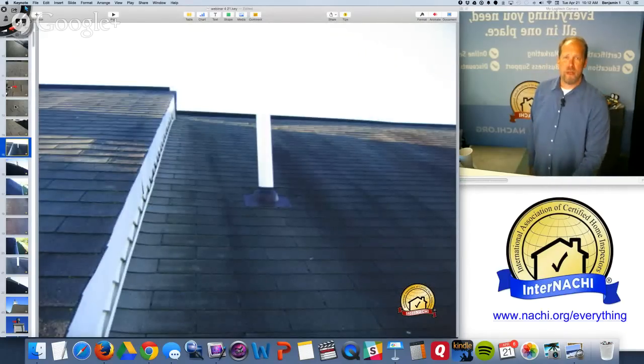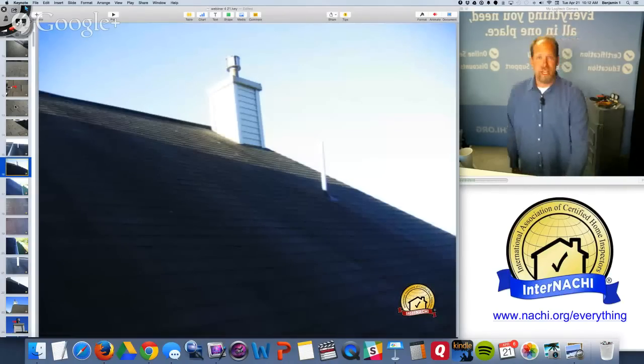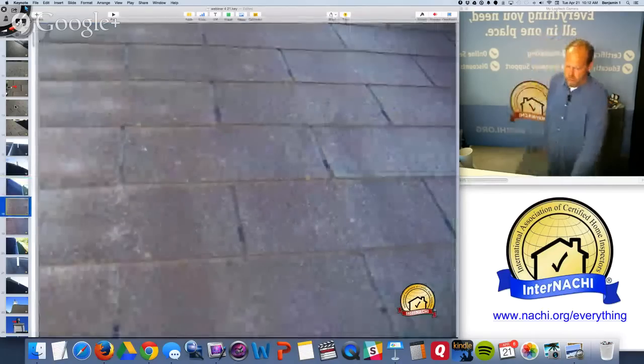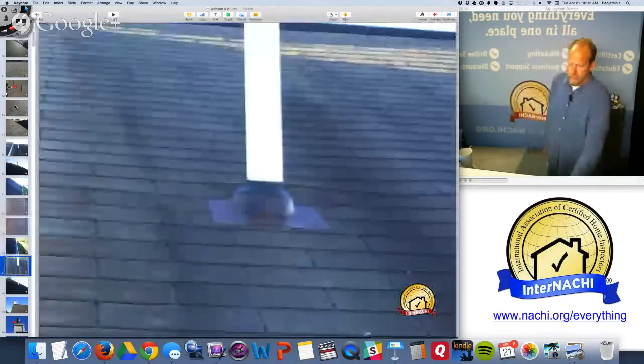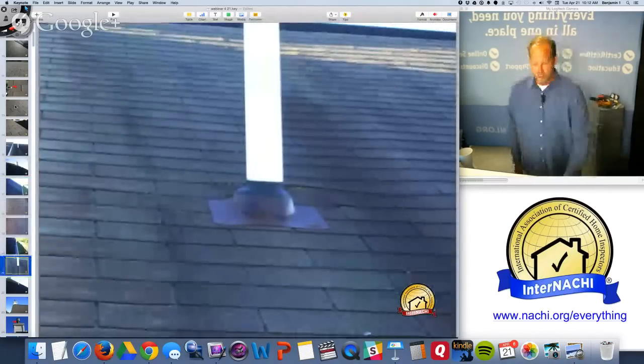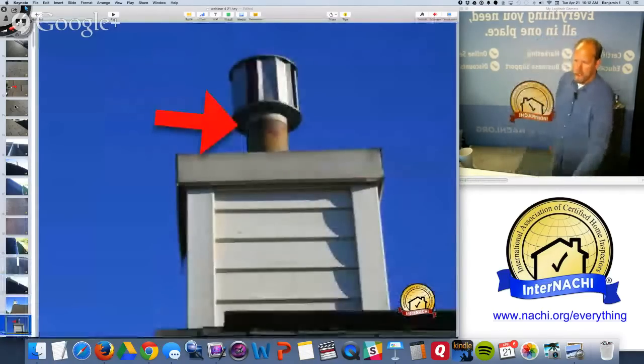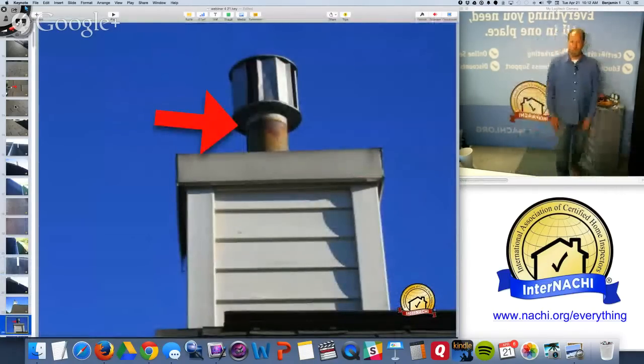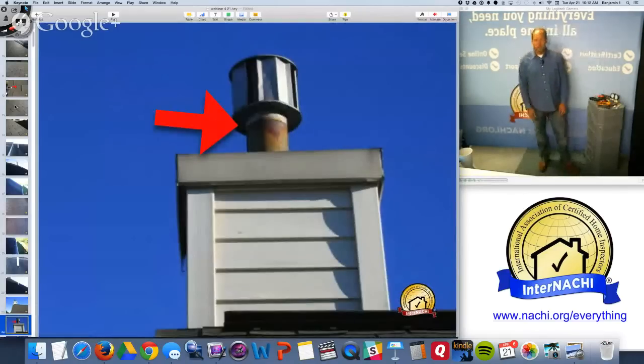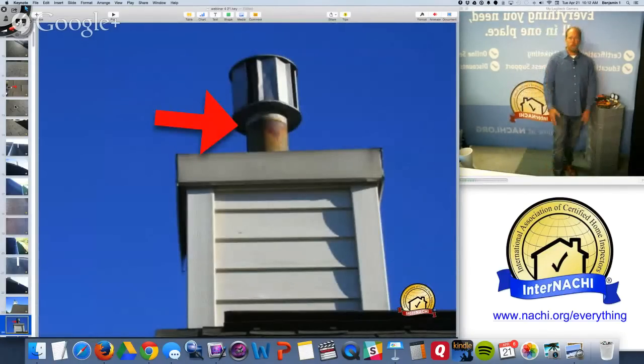You're required to inspect the flashing around anything that penetrates the roof covering material. There's a chimney, that's part of a roof penetration system. And it looks okay. Backside's in shade, that's why we have discoloration and a little bit of moss growth. No big deal, cosmetic. Some corrosion, galvanic corrosion. We have a course that describes that, a couple articles.